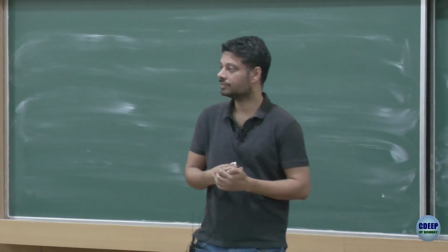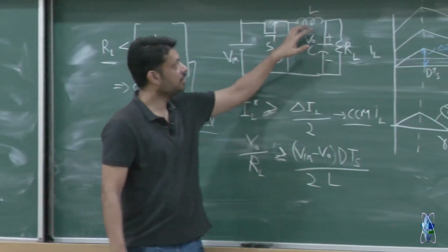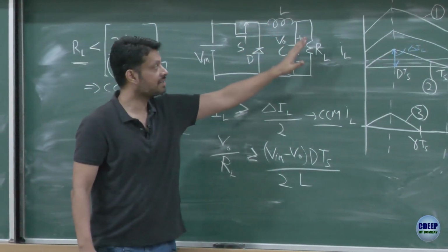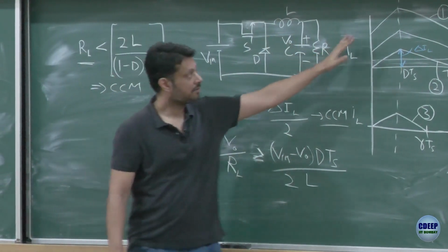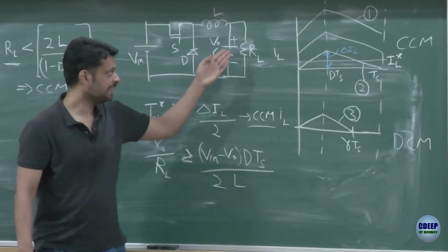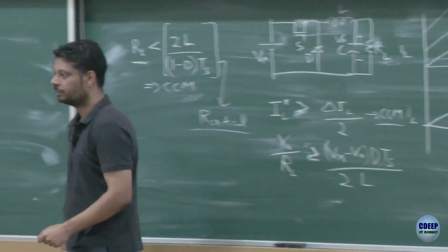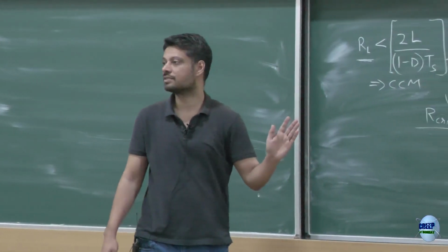No, that's what I am saying, right? Your converter is producing the voltage and the current is determined by the voltage. The voltage is constant from case 1 to case 2. You are changing the load resistance, current is changing accordingly, V by R. Any more questions?